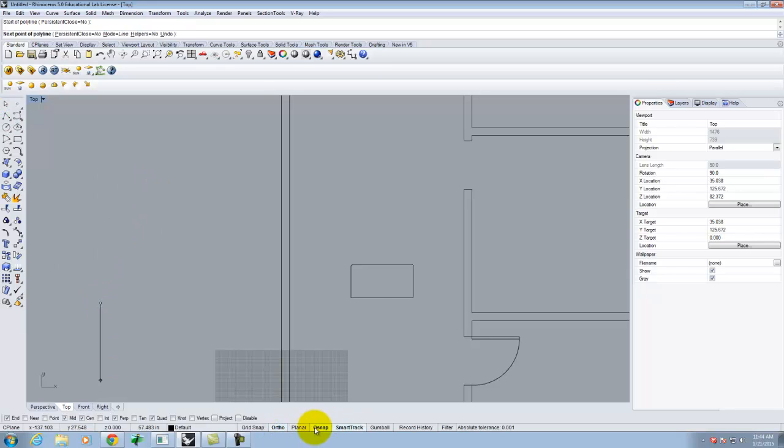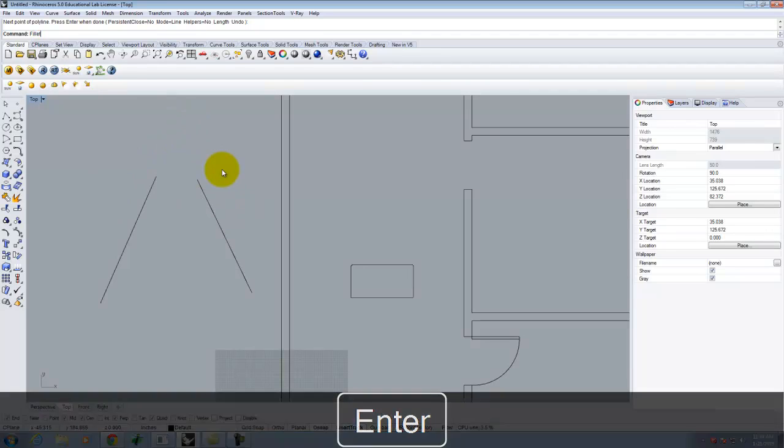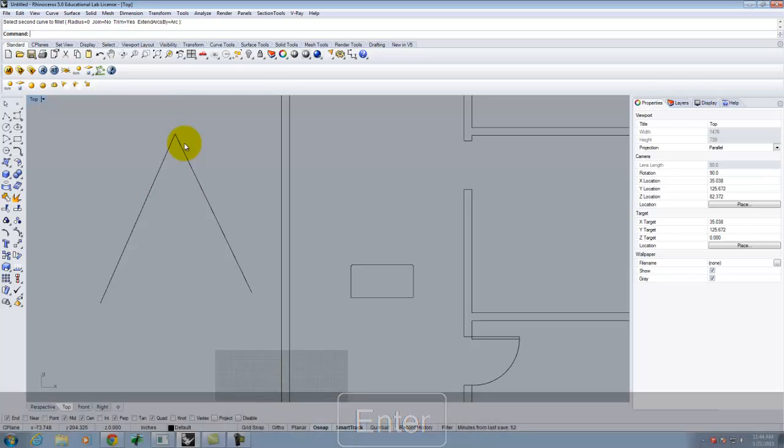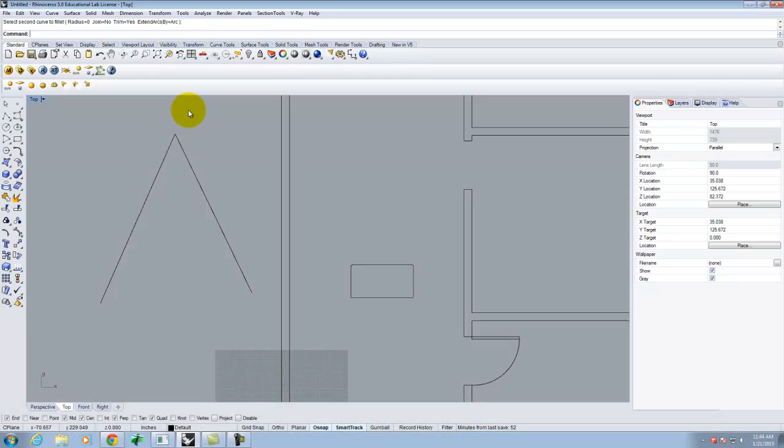you have lines that you want to come together, right? I would like these two lines to meet in a point. It's hard to make that happen. I can use fillet without a radius, so I set a radius to be 0, and then I can connect those two in a point. It's just a really fast way of creating a point.